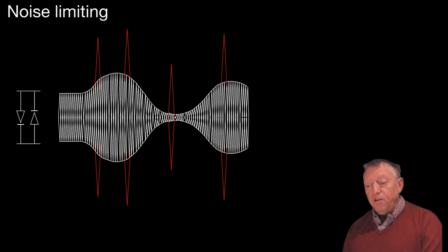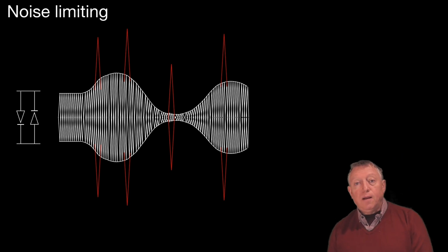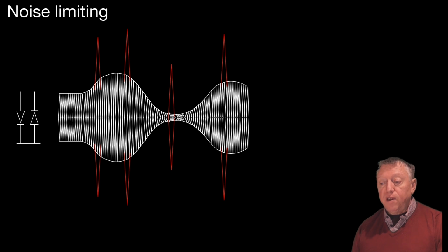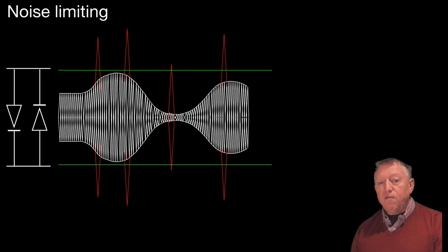One of the methods used is very simple. It's simply two back-to-back diodes. And you will recall that diodes have a need for about 0.6 volts forward bias before their PN junction will allow the flow of electrons. So if we put two back-to-back diodes facing different directions, anything above 0.6 volts, whether it's a positive half cycle or a negative half cycle, will be conducted away. So this has a way of clamping the voltage to 0.6 of a volt.